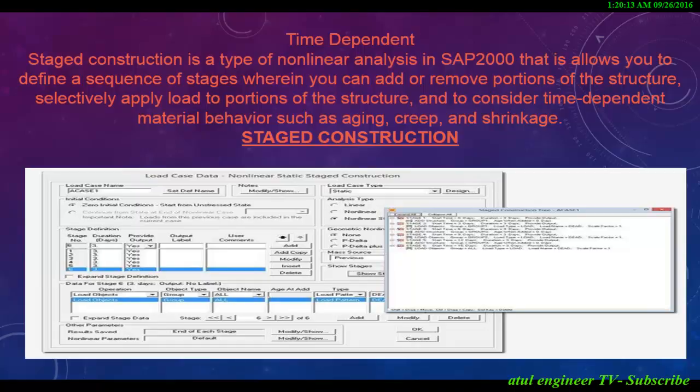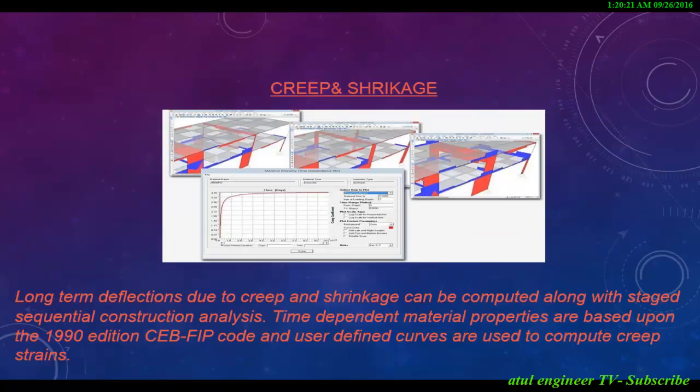Time-dependent. Staged construction is a type of nonlinear analysis in SAP2000 that allows you to define a sequence of stages wherein you can add or remove portions of the structure, selectively apply load to portions of the structure, and consider time-dependent material behavior such as aging, creep, and shrinkage.